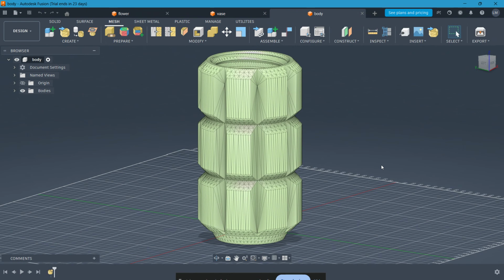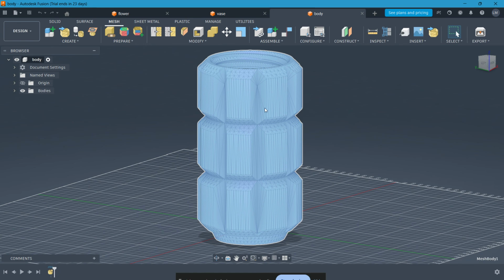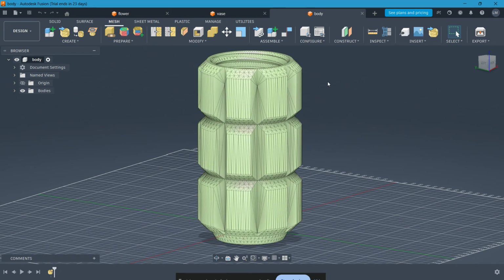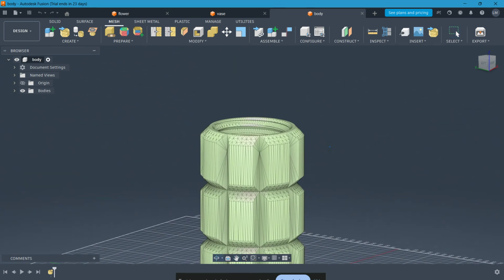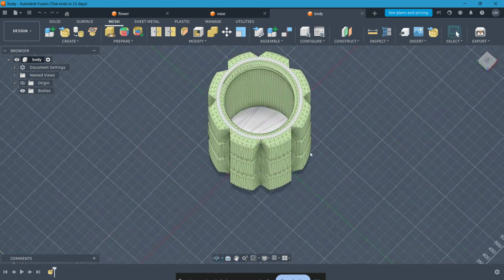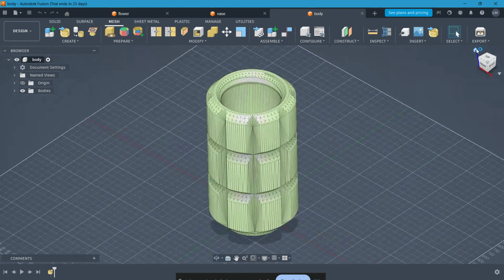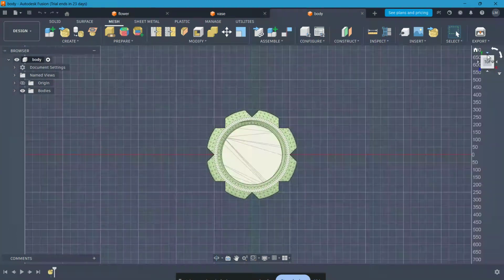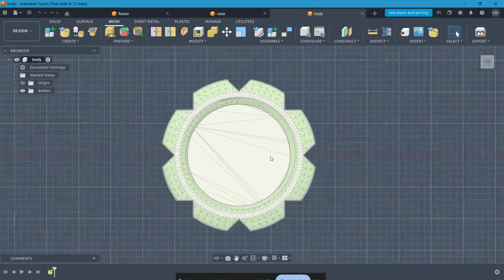So first, what does this error actually mean? The phase solid meshing error happens when Fusion 360 fails to generate a mesh inside your solid body. In simple terms, Fusion can't properly fill your model with simulation elements, which means the simulation can't run. This usually comes down to problems in your geometry. Let's go through the most common causes and how to fix each one step by step.